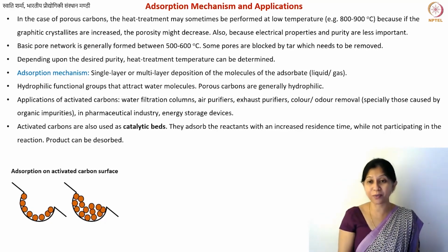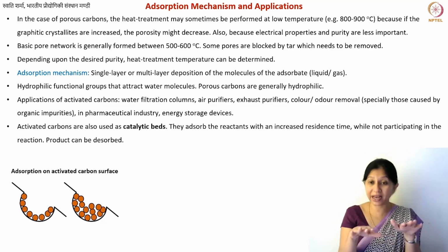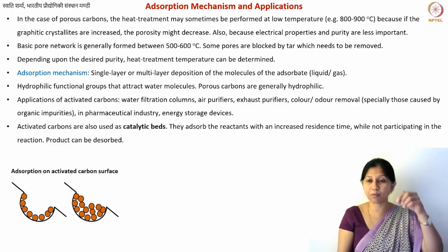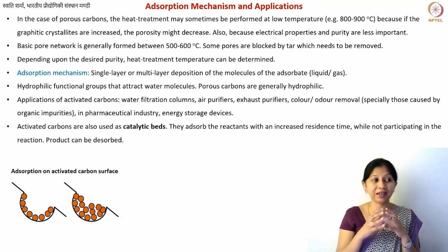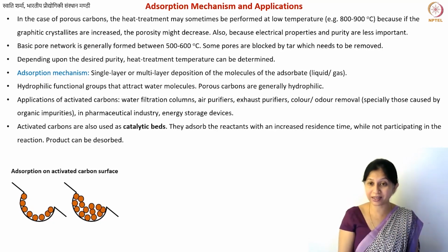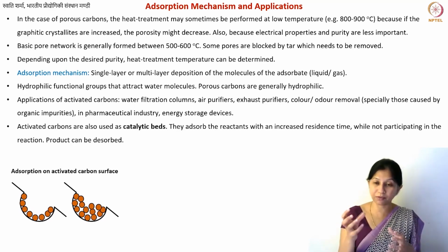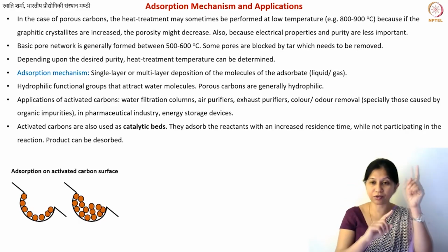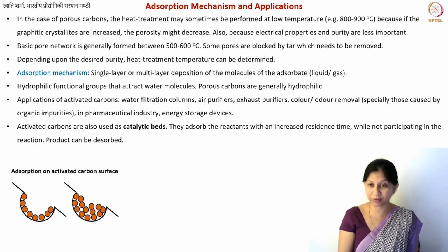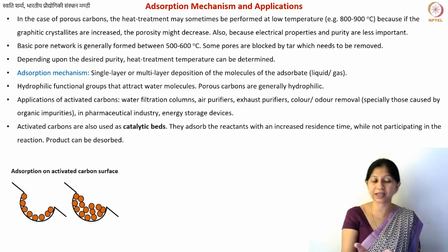Or you can also provide a solid support for this reaction. So you take an activated carbon bed, on top of that you add both your reactants and the catalyst, and then this increases the residence time. Residence time means the time where all three entities can interact. In the solution they are always moving, but here they have a solid support. And if you have pores of this kind, then inside these pores you can trap the molecules of whatever reactants you have, and also the catalyst.